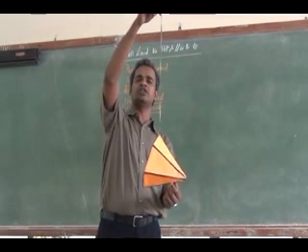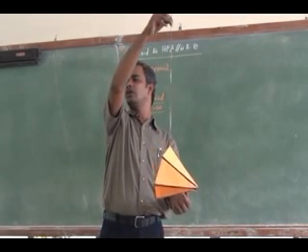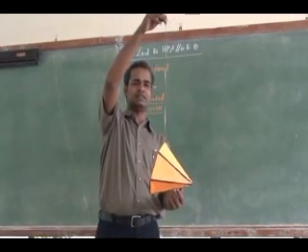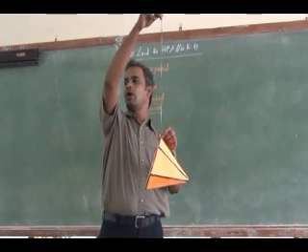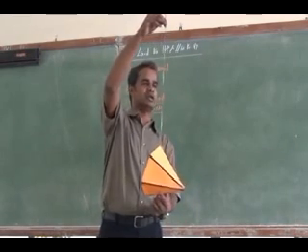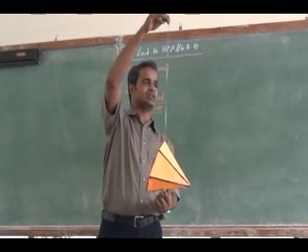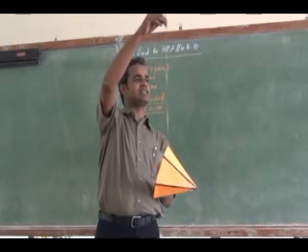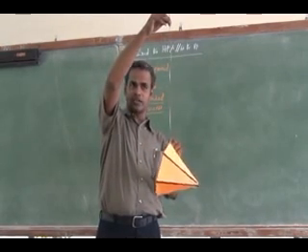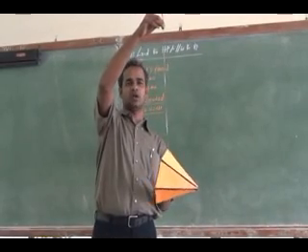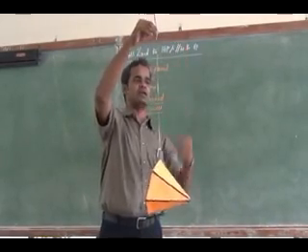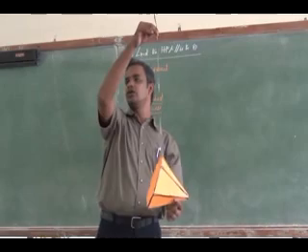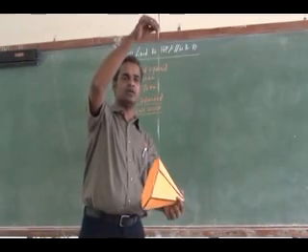So in what orientation it is hanging, that is very important in this one. Any solid, if I hang it like this, the tied point and the center of gravity of the solid, the centroid of the solid. If I connect them with an imaginary line, joining the tied corner and the CG, it will be vertical. It will be vertical.